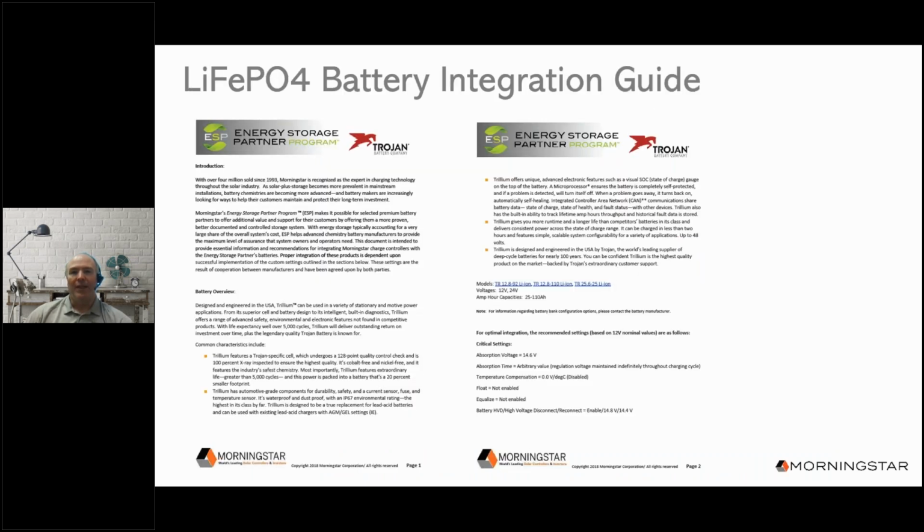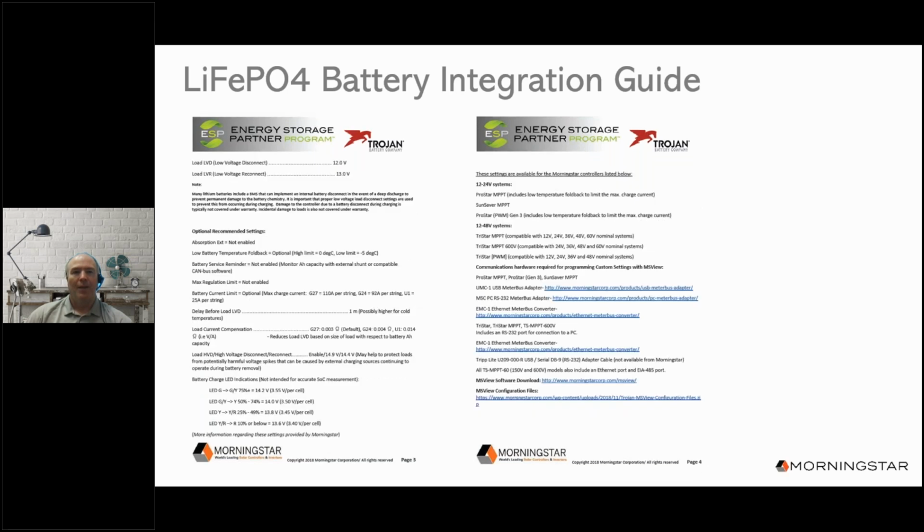Here you see an example of an integration guide. We provide an overview of the lithium battery brand, and then we provide optimal controller settings that you should input concerning absorption voltage, also battery high voltage disconnect and reconnect set points. We also provide battery current limits and other optional recommended settings in addition to links to configuration files. So there's lots of good information on the Energy Storage Partner Program webpage. And if you're using lithium batteries or thinking about using lithium batteries, you'll definitely want to visit this page.